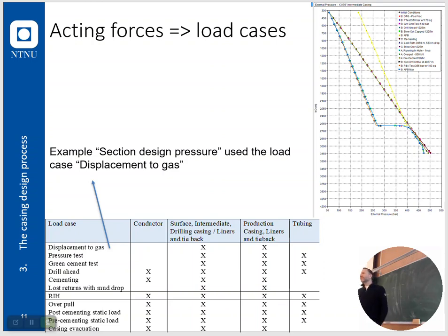Because the gas lift will go to a certain depth, and then there is a check valve there. So from that check valve and up, you will have nothing in the annulus. And in the tubing, you may have a fluid, and in the annulus of the gas lift casing, there will also be a fluid. And you need to understand what this means.